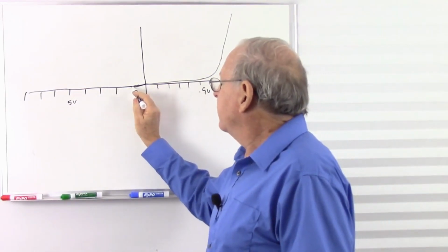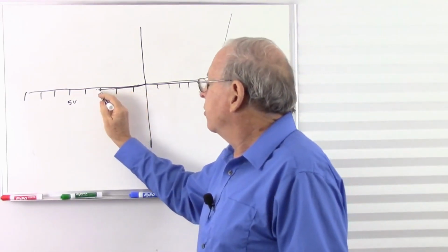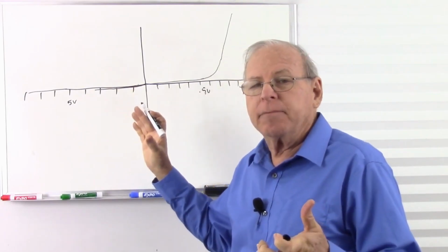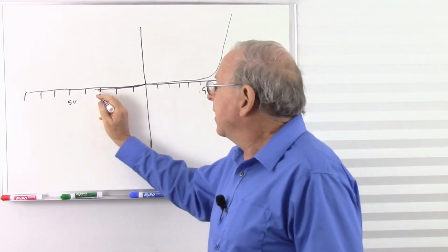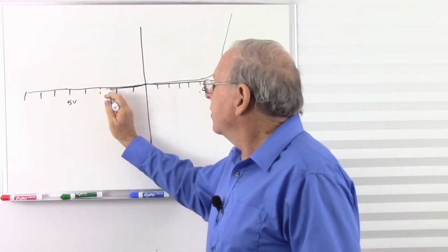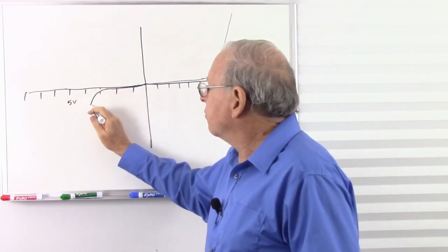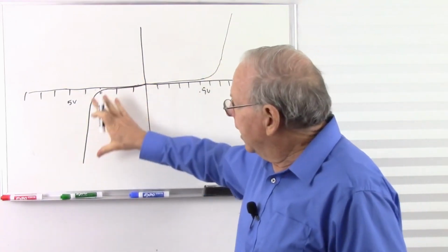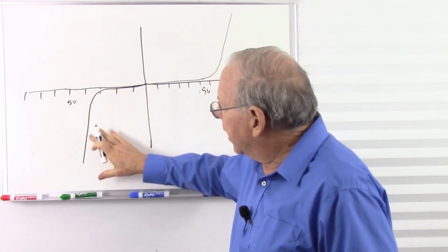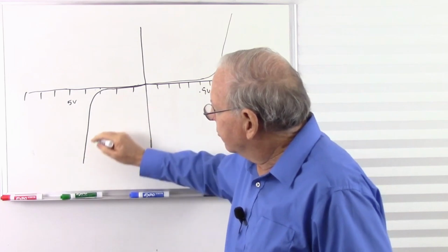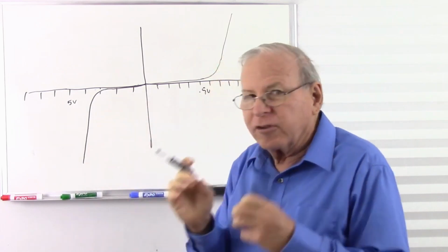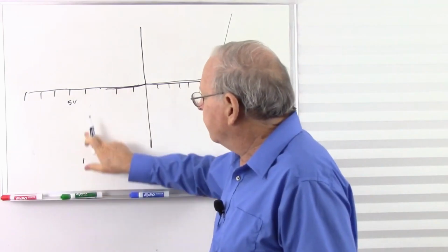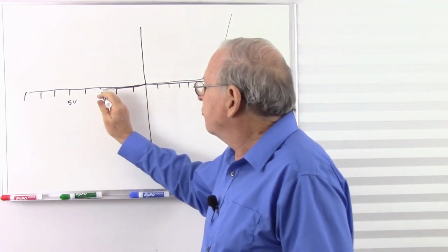As we reverse bias it, we get hardly any current, no current, no current. Now at lower voltages, like if we have a Zener diode that's rated at maybe 3 volts, it's going to make kind of a lazy curve as it goes around. And so lower voltage Zener diodes are not really that sharp in their breakdown and in their conductance. It gets kind of slopey here, so they're not quite that precise. But as we get higher and higher in the breakdown voltage, or the Zener voltage, that gets sharper and sharper.